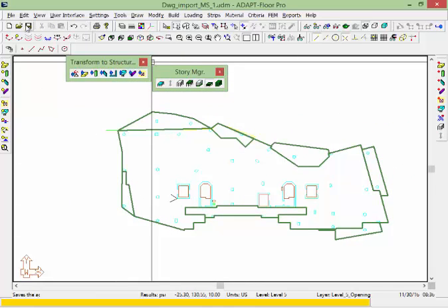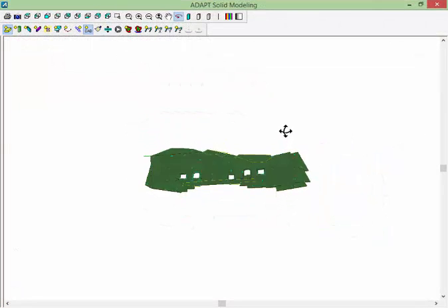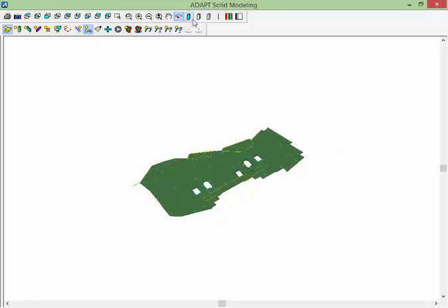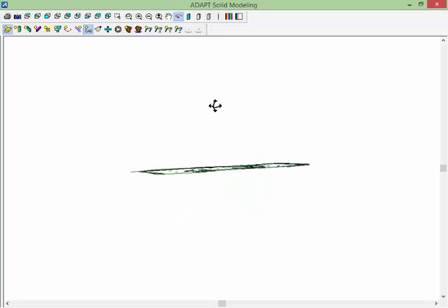If you want to review this as you build the model, I typically would recommend you use the option for View Model, the model viewer. This shows you what you have in place at that particular level. You can actually see the CAD file. If I turn the CAD file off or on, you can see it stacked on top of the actual model in this view.